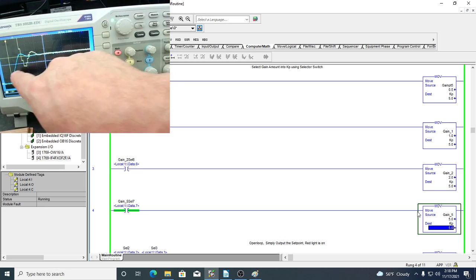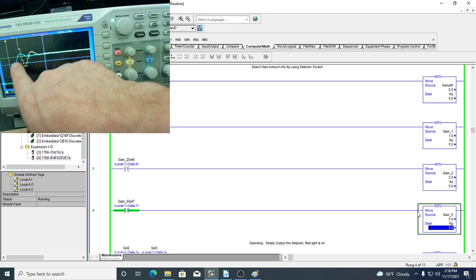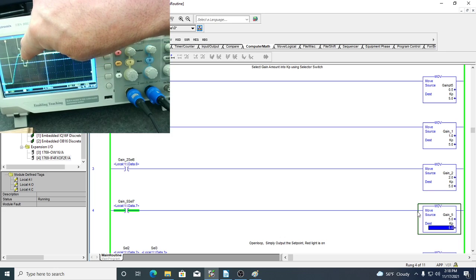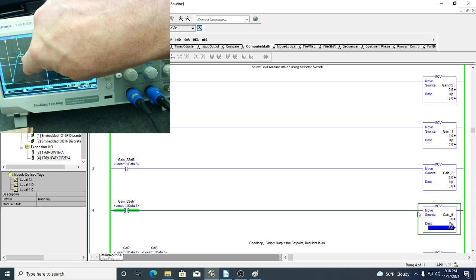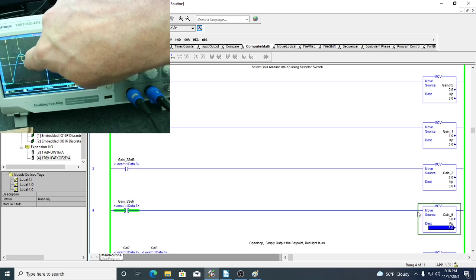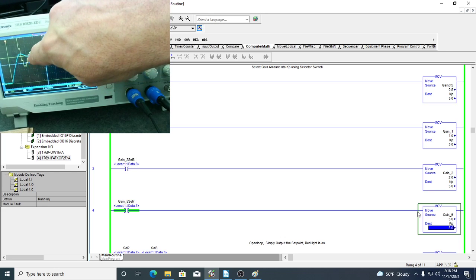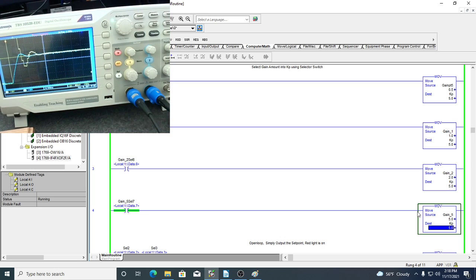So again, this is on the 1 volt, and you can see it's cut off at the top here, but once we reach it, we're already kind of bringing the control system back down, trying to push it back down because we know we overshot, and then we go under, we push it too low, and we get these oscillations. So this will happen when you start increasing your gain. The more you increase your gain, the more oscillations you can add into the system, and the more overshoot you can have.